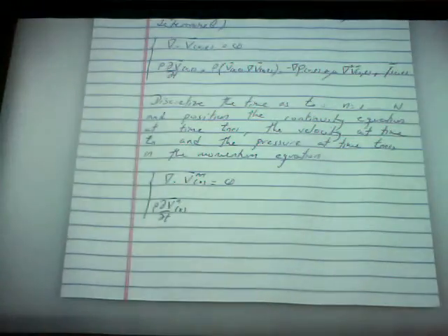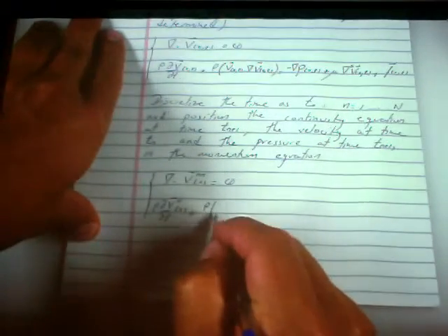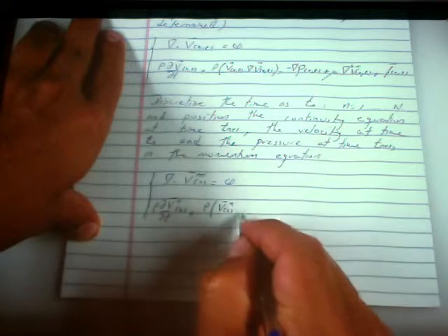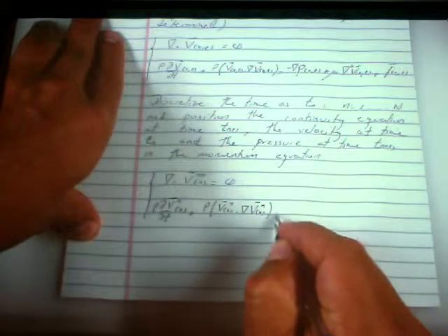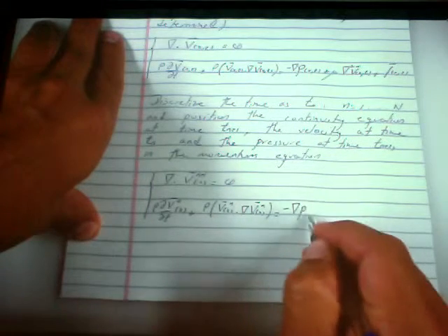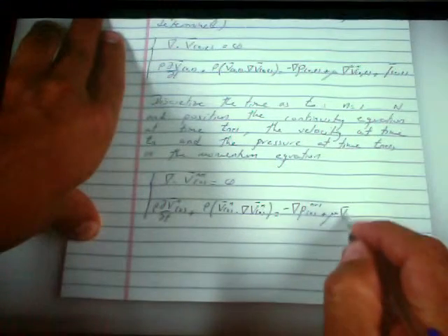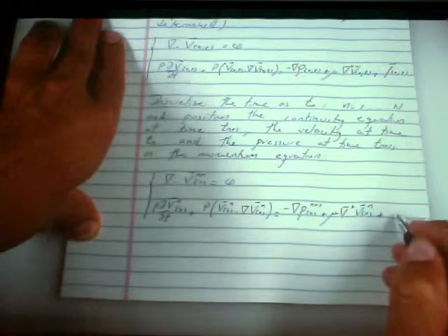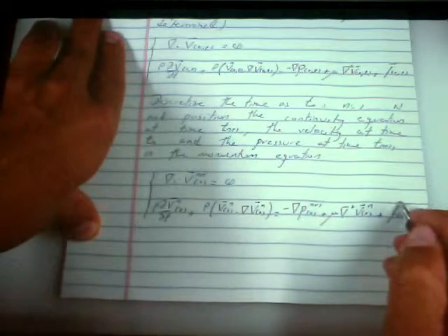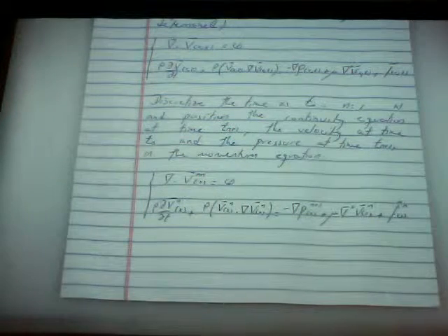Notice that I'm eliminating t, so I'm discretizing the time. Plus rho Vx at n, gradient of V at n, and I am purposely positioning the pressure at n+1, plus mu Laplacian of V at n plus F at n. The body force is a known quantity. All right.